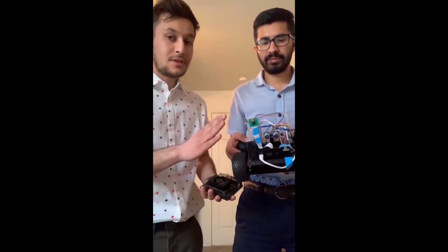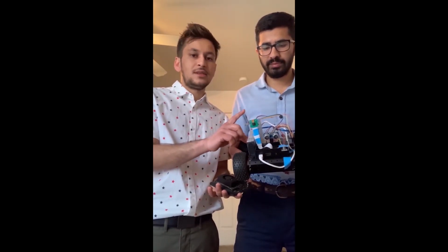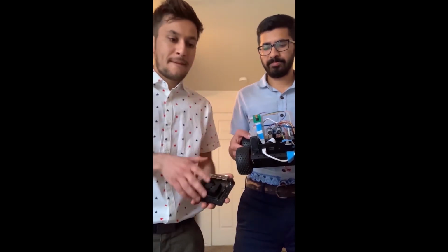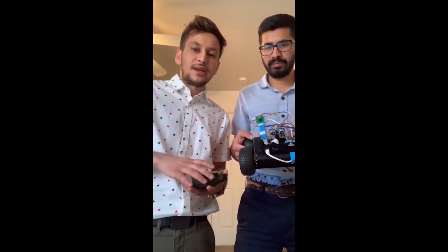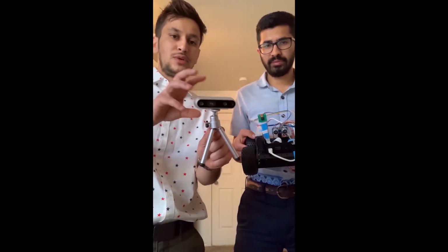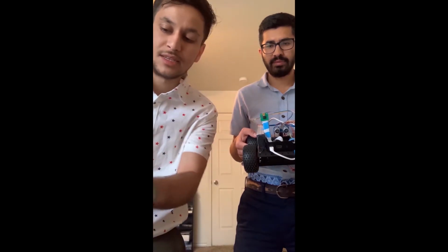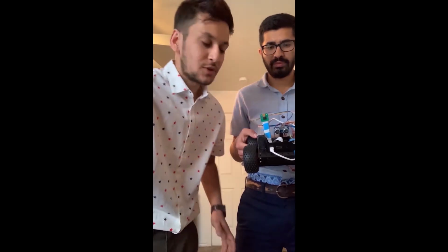Okay, now let me talk about the future plan of our prototype. This prototype is in perfectly working condition, but it has some limitations. The first is that it is using a two-dimensional camera, which can only sense two-dimensional data of the environment. In the future, we are planning to use an RGBD camera, which can generate three-dimensional data of the environment to better sense the environment and send all that data to this controller.